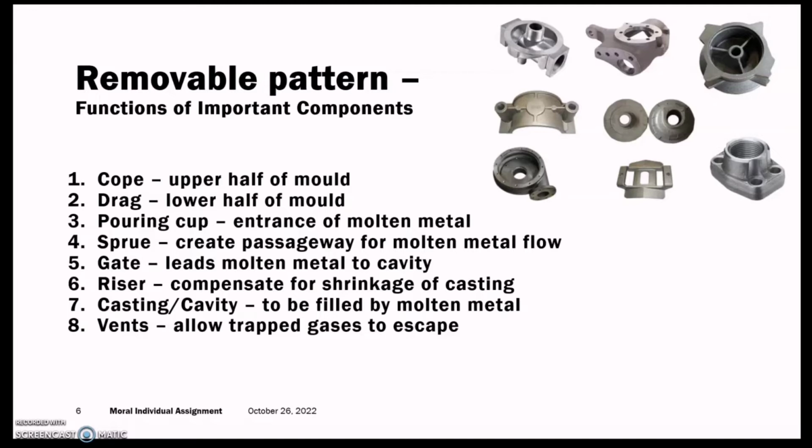Riser, to compensate for shrinkage of casting. Some metal will shrink when it solidifies. And the molten metal in the riser is the last to solidify, or never solidifies, to supply molten metal to the cavity, because the riser itself is made out of metal.